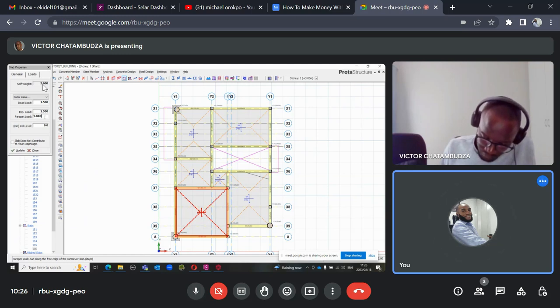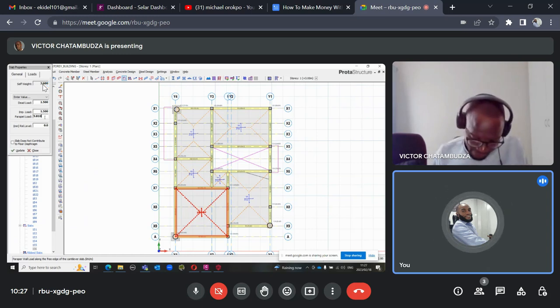No, 2.825. Okay, yeah, I used to use 2.825. So if I get 2.825, that gives me 9.802 something. So I just said 9.81. So that's how I take my story height to be 2.825, so that in case they use their story height to be 3.2, by the time they subtract that beam depth, they will have up to 2.8 something. So I am still safe.